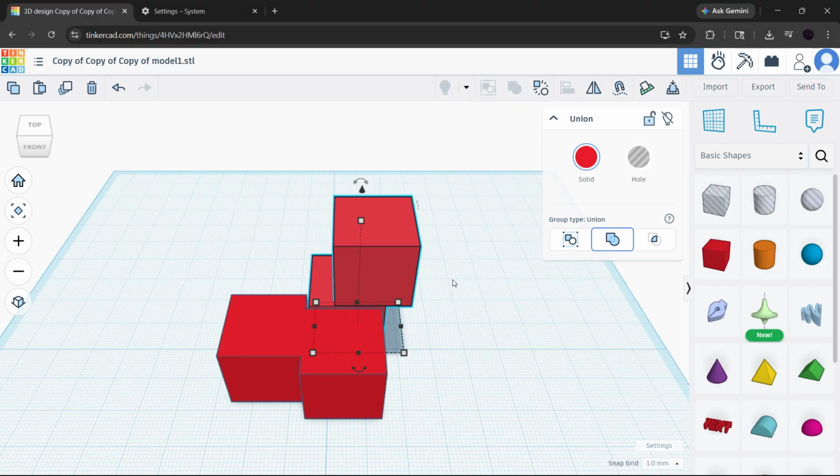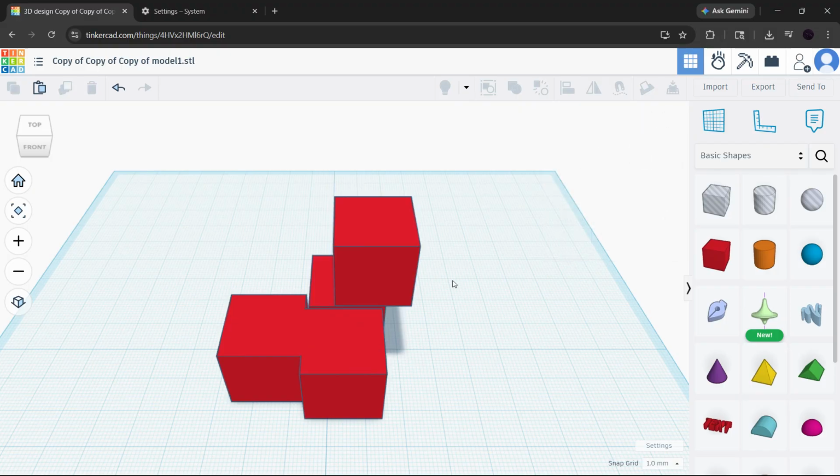And if you just grouped something a moment ago and it suddenly broke, the better option is usually Ctrl+Z instead of using Ungroup. Undo works locally in your browser RAM, so it is often more reliable than the server-side Ungroup command.